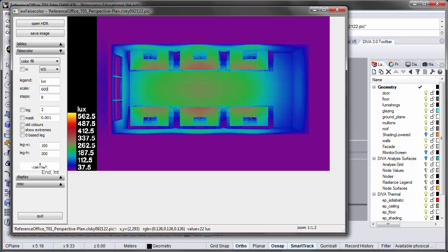So after a couple of seconds, you'll see that it converts the image to a false color reading, where every pixel corresponds to a lux value, and it also has a color value now that we changed it to false color, ranging from 0 to 600. So I can go ahead and click on these various portions of the scene. Like right at the edge of the table, you'll see that it's very close to 300 here, and we have over 300 lux, and so forth.